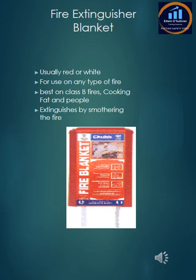Since the invention of the electric car, these fire blankets have taken on a new role within the fire service. They have them on site now in some fire stations, and they're approximately 6 meters by 6 meters. An electric car fire will take approximately 10,000 litres of water to put out. With this fire blanket, they will walk it up over the car and start walking in, surrounding the car with the blanket, and it will put it out in a matter of minutes with no water whatsoever.